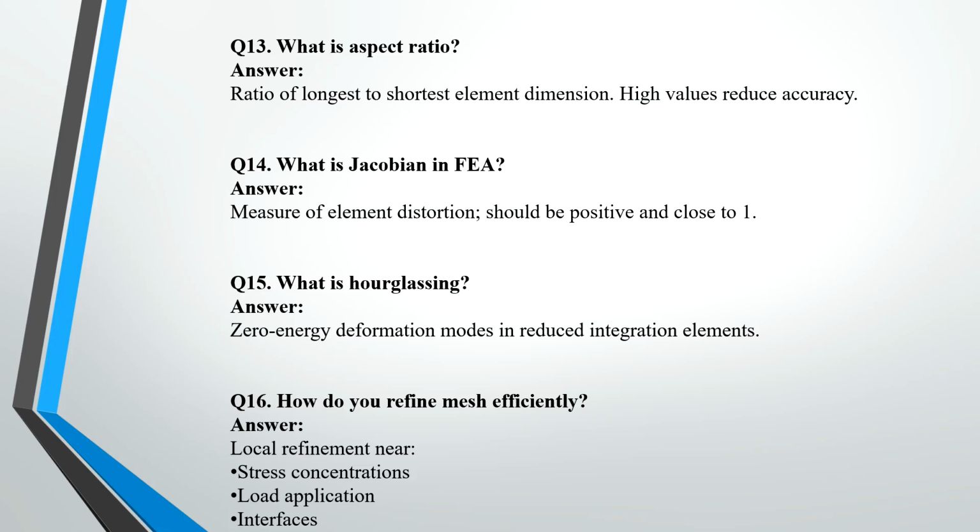How do you refine the mesh effectively? The answer is local refinement, like near stress concentration regions, the load applications and interfaces and so on. So we need to have a refined mesh there.